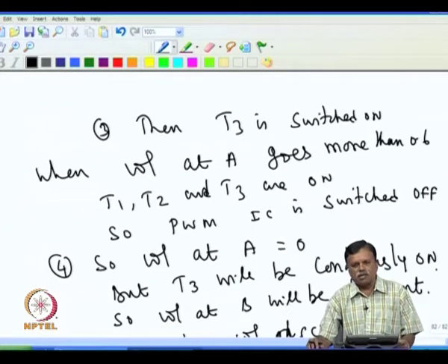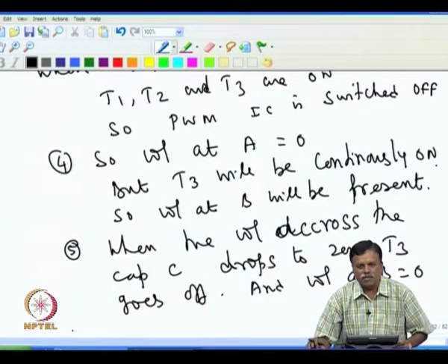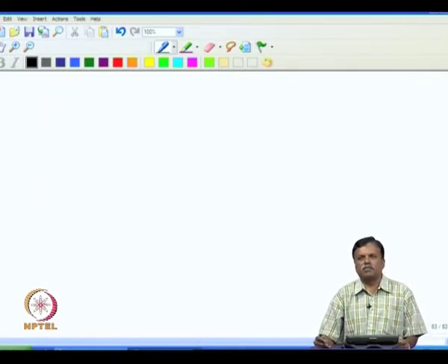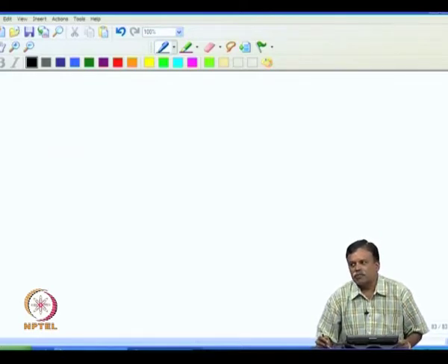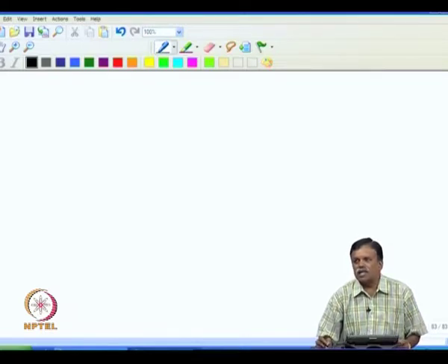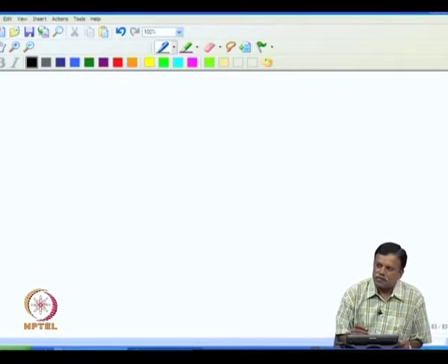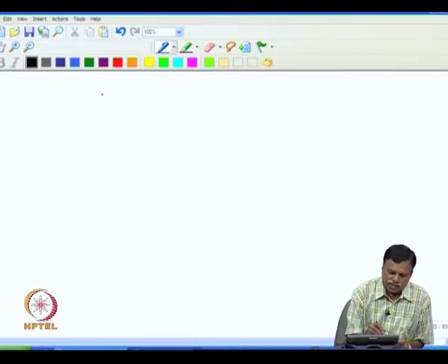Now, the transistor also can be used as a temperature compensating element, because in many cases, for example many transducers, when temperature changes, the property of the transducer changes, and we want to make a temperature compensation. We can use the transistor effectively for this, because the base emitter voltage of the transistor changes with temperature. That can be used to compensate temperature change of some other transducer. So, how to use the transistor for temperature compensation, we see in this example.